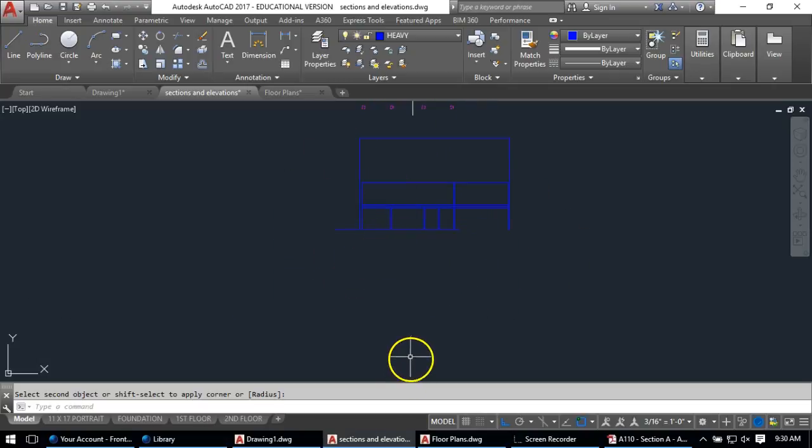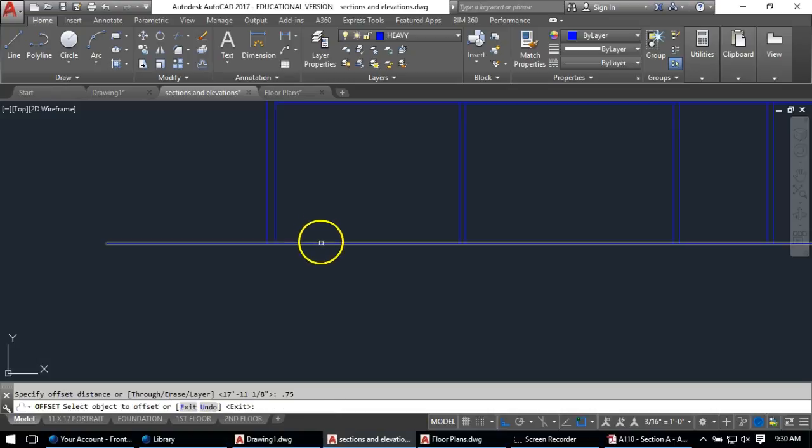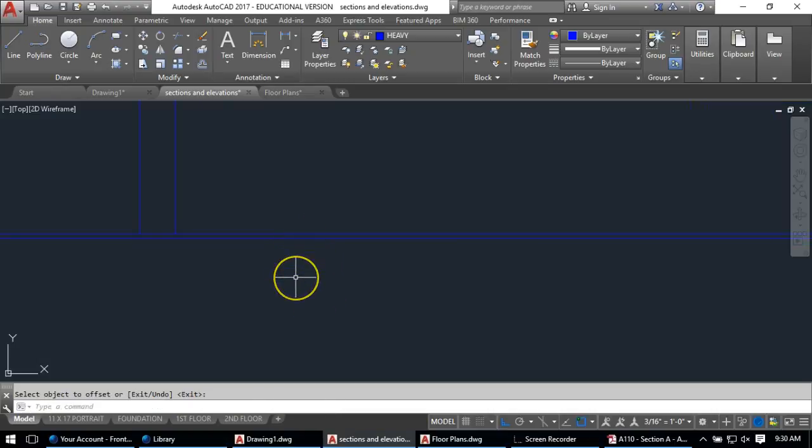Of course, we need to go down to the foundation as well, and we sort of need to do the same thing here. So I'm first going to have some sort of unknown finished floor that I'm calling 3/4 of an inch, so I'll offset down 3/4 of an inch. We'll offset another 3/4 of an inch down for the plywood subflooring. Then we have our joists, which are 2x12s again, so it's 11 1/4 inches, and that'll be there.